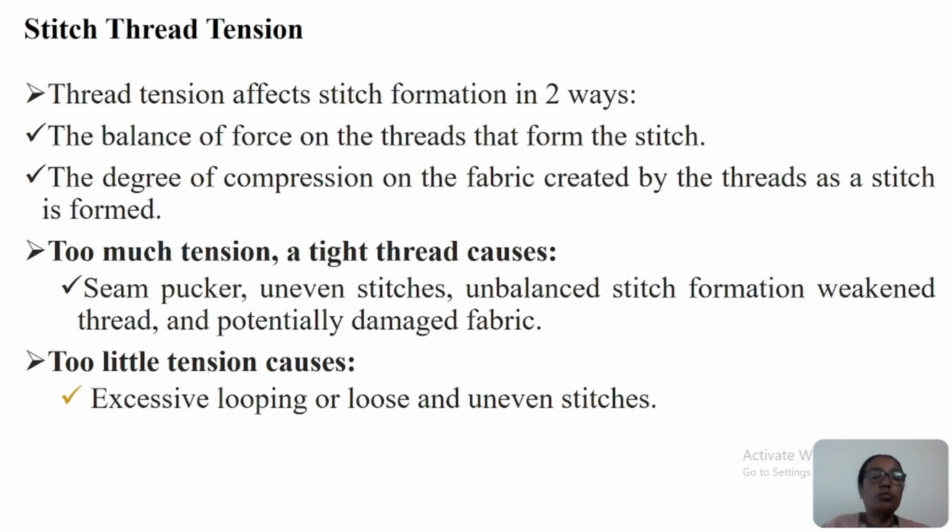When the stitch has too much tension or a tight thread, it causes seam pucker, uneven stitch, unbalanced stitch, formation of weakened thread, and potentially damaged fabric. Maybe the tension of the thread is too much or a tight thread.